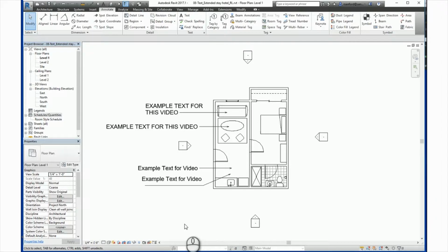Text notes automatically scale with a view, and since most designs end up on paper for drawing sets, etc., it is often necessary to modify text properties and format them such that they meet certain standards, organization or otherwise. Type properties pertain to properties that affect all members of a family or instances of a particular style. For text notes, these properties relate mainly to their appearance.